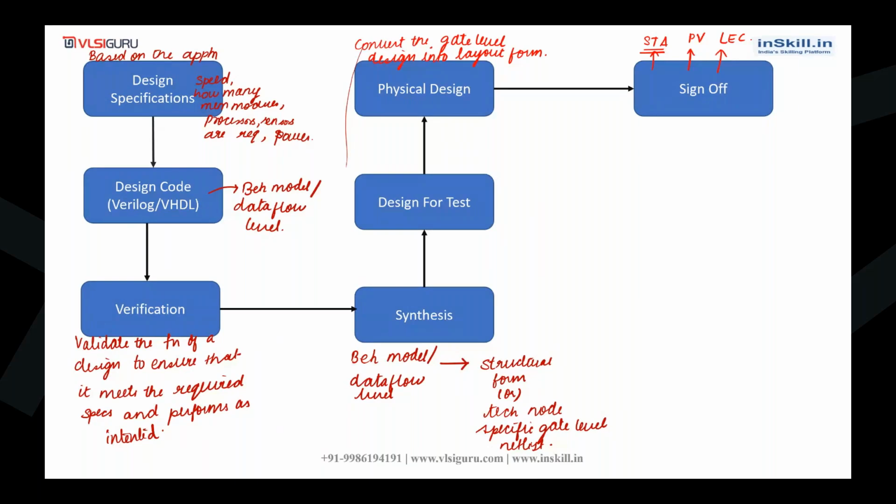And then we have the physical verification, PV. It is actually to verify the layout of the circuits. And then we have LEC, logical equivalence check. Logical equivalence check, LEC, is done in order to check whether the final design is logically equivalent to the original design.